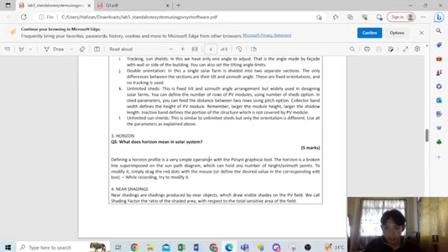The horizon can also affect the azimuth angle, which is the orientation of the solar panel with respect to true south. If the horizon is obstructed by a building, tree, or other object, it may be necessary to adjust the azimuth angle to compensate for the shading.